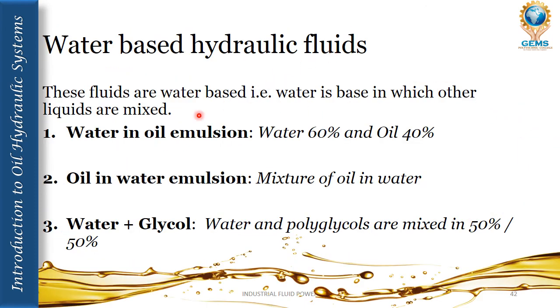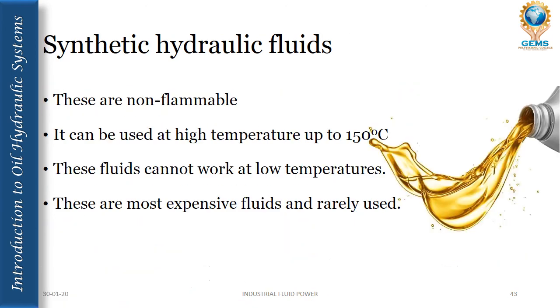Water-based hydraulic fluids. These fluids are water-based, that is, water is the base in which other liquids are mixed. There are three types: water in oil emulsion, that is water 60% and oil 40%; oil in water emulsion, that is a mixture of oil in water; and water plus glycol, where water and polyglycols are mixed in 50%.